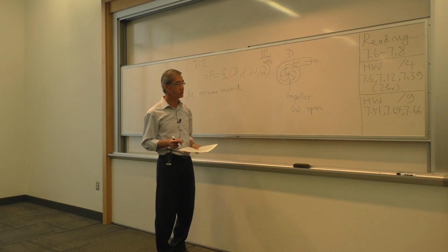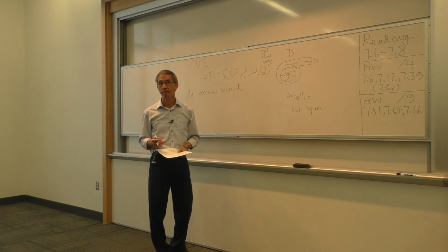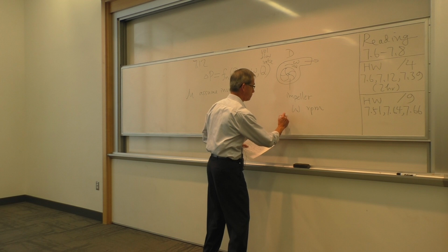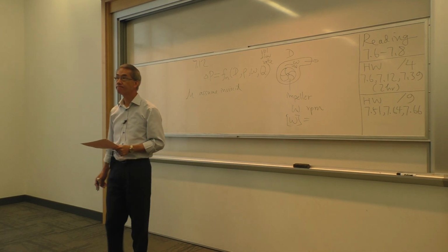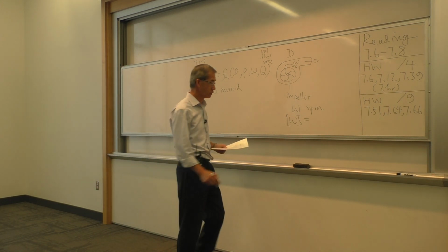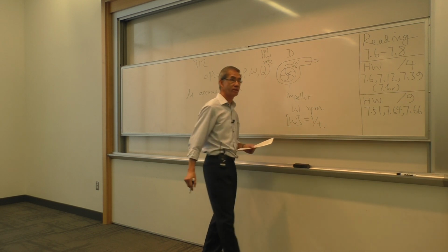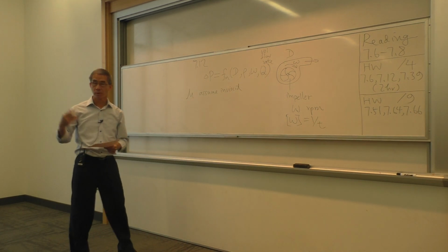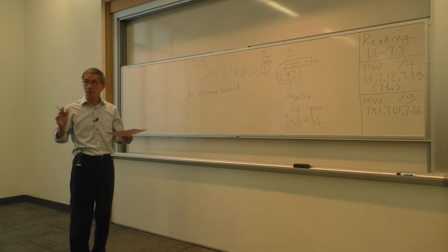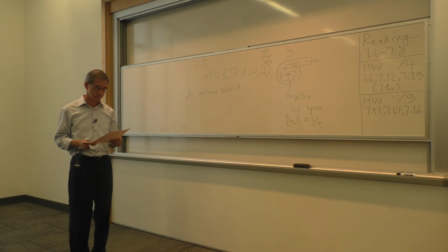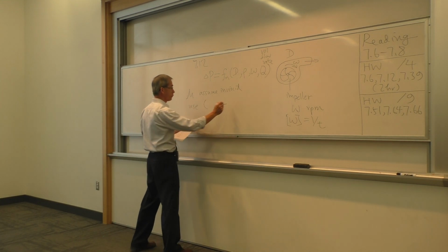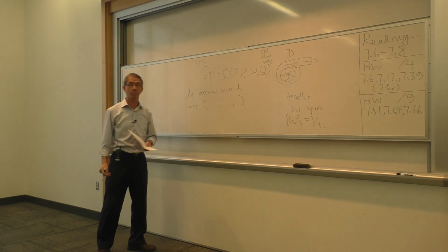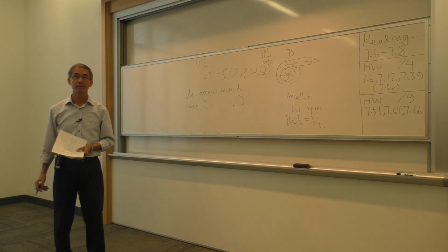First, what is the unit of RPM? Revolution per minute, the unit? It's 1 over time. Radian or 2 pi radian for 1 rotation has no unit. So make sure you don't make that mistake. If you cannot get the fundamental unit, you cannot get the right answer. I now need to decide what 3 dimensionally independent terms I want to use to find the pi term.